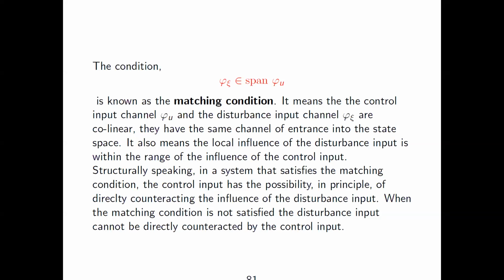For a DC motor, if your power is drawn from a battery, that's fine, you just have a constant voltage. But what if your energy is drawn from a wall outlet, and it has to go through some rectification device to transform the sinusoidal function into something that ideally should be flat, but in reality, because you use some capacitor, it has certain fluctuation.